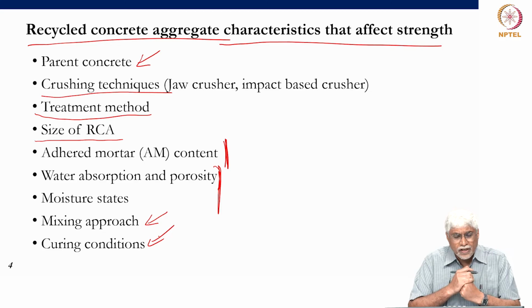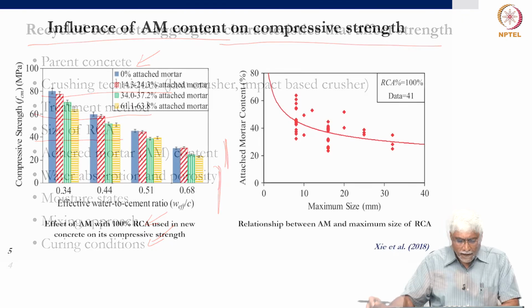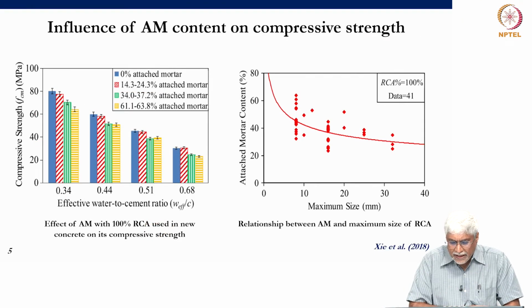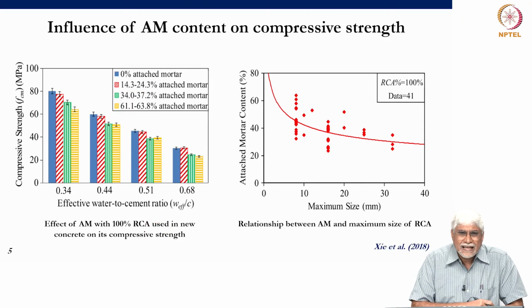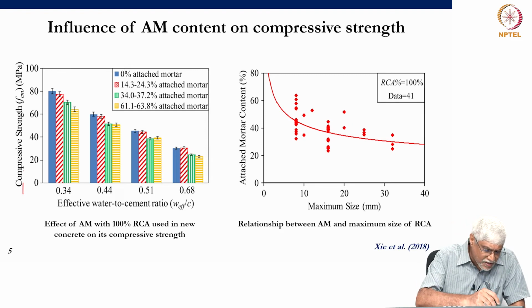When we cure concrete, we are allowing time for the cement to hydrate, for the interfaces to become stronger, and therefore concrete behaves much better. The strength is better, shrinkage is less, and creep would be less. So let's look at some results from the literature on different aspects of recycled concrete aggregates that affect the compressive strength. So on my left, I have the relation between compressive strength,